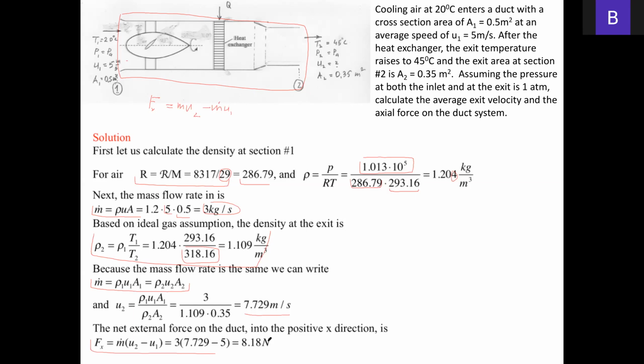Okay. Professor, how do we know when the mass flow rate is the same going in and coming out, or when it's different? If you look at the problem, we have a continuously operating system, and there is no reason for the fluid to accumulate. If it keeps accumulating, the pressure will build up and it's going to blow up. So it looks very logical that whatever goes in comes out at the other end, because it's a continuously operating system. Do you agree to that? Yes, so it's safe to assume it's always the same coming in and going out? It has to be the same, because we discussed with the stream tube that whatever goes in goes out. Otherwise, we have to leave something in.